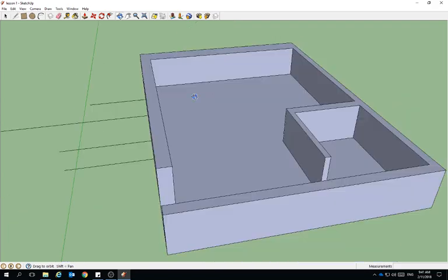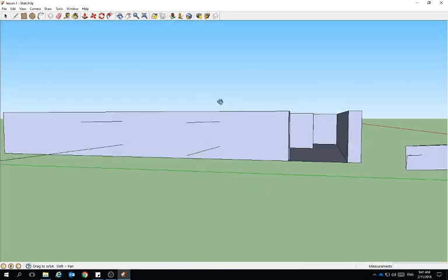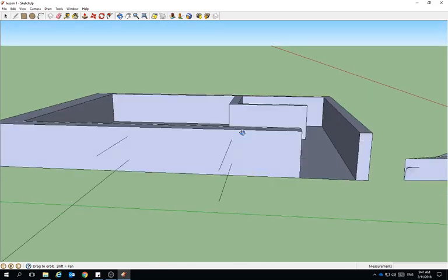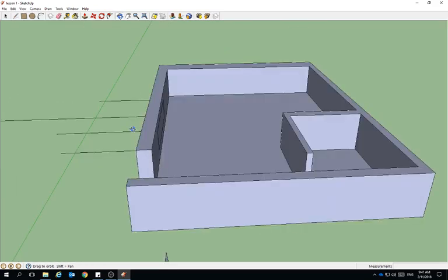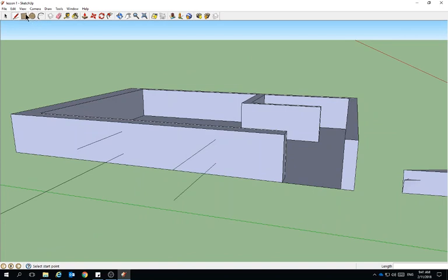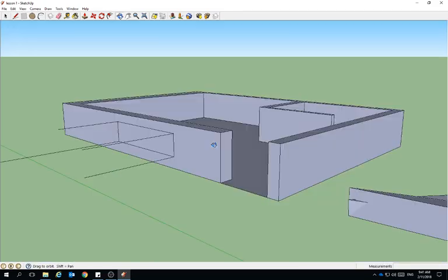So when I change my angle that I'm looking at, you can see that I've now got 4 points coming out of that wall, which are going to line up perfectly with the rectangle I did on the inside. And this is where you'll see another type of snapping tool. So before, we've had the blue, the red, the green, and the light blue for the midpoint. Now it comes up with a red cross and it says intersection. And that's where a line comes through a solid surface like this rectangle you're looking at right now. So if I click on that, I go down to the other one. All right, and I've now got my two rectangles lined up perfectly with each other.